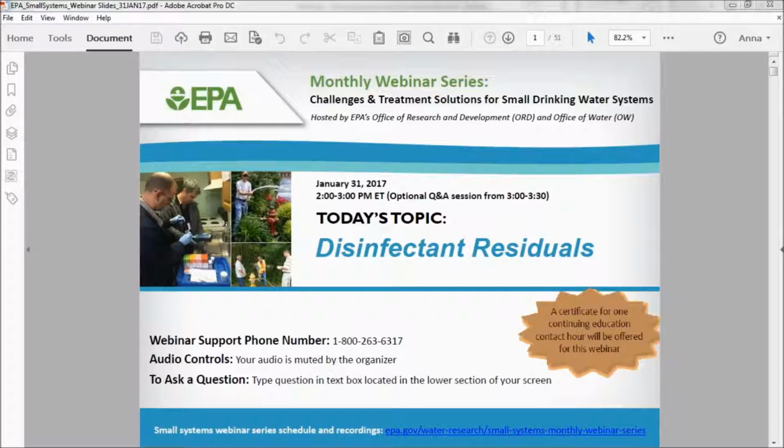As I mentioned earlier, we like to use a factor of safety to ensure you're getting to the main. You don't want to overflush, like one of the questions I answered earlier, because that might provide biased results. But you don't want to underflush either, because then you're not accurately characterizing the water in the main; you're characterizing water in the service line. So we recommend using that calculated flush time procedure.